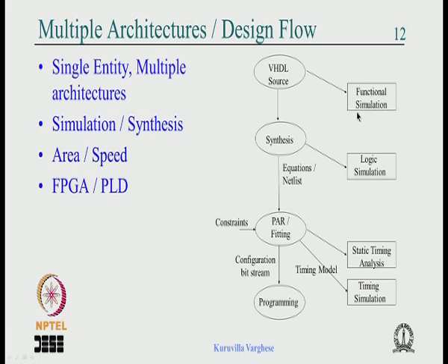When you simulate, if one of the inputs changes at 100 nanoseconds, the output also changes at 100 nanoseconds, because we have not used any device yet. There is no delay and no mapping to the device. So functional simulation and logic simulation are kind of zero delay simulation, because it is just the bare logic, which is not fitted into a particular device.